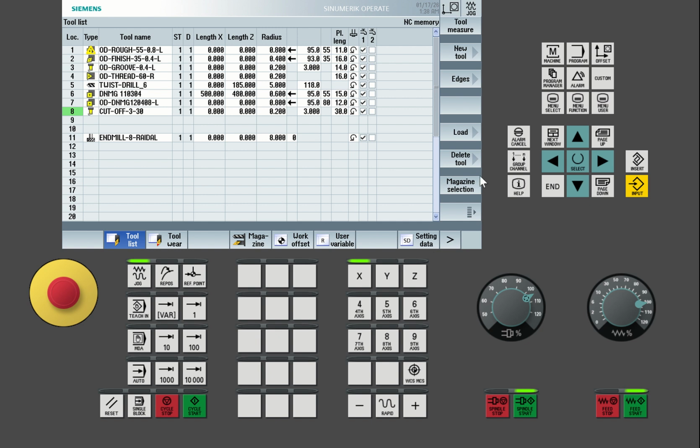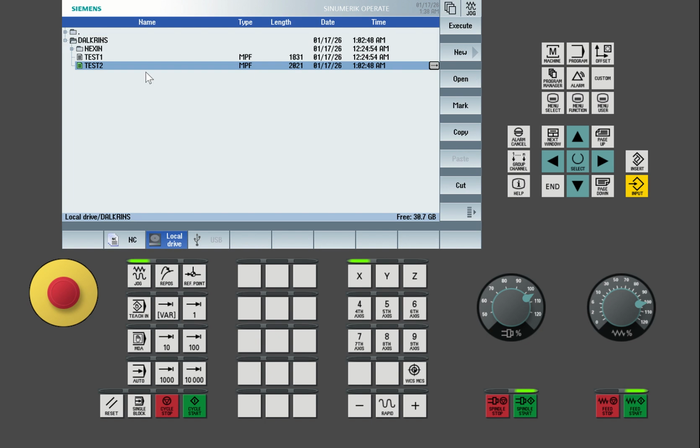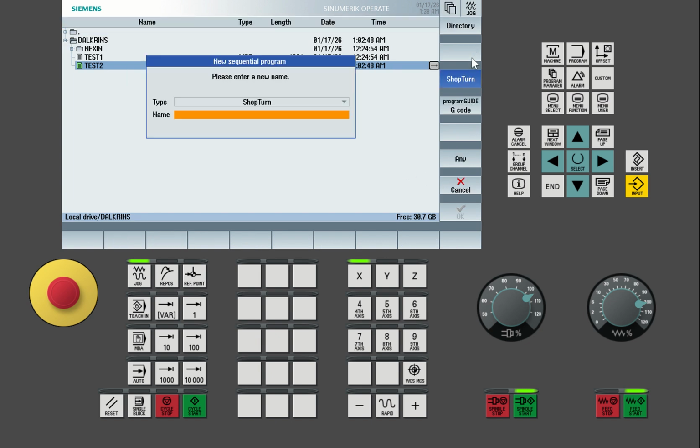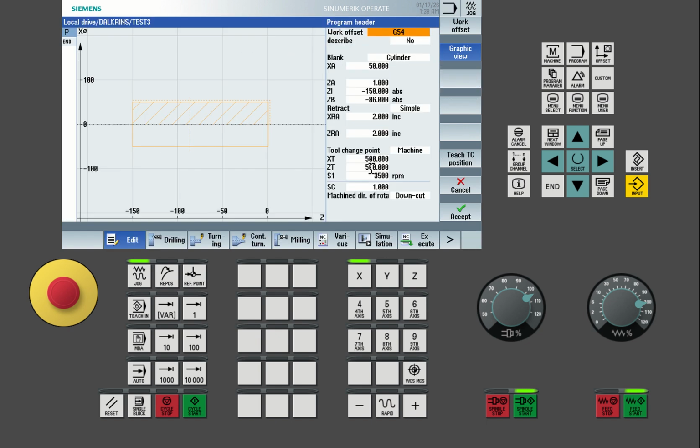So let's go to program, go to program manager, and then click on new. Ensure this is test 3, then click OK. When it comes on, we have our diameter of 48, so I'm going to use 50. With the facing of 0.1 amount to face, then safety, the total length for the stock is 150. Cutting almost to, let me put minus 105. This can be minus 160.